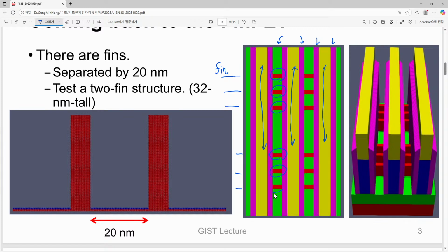Later, on top of these silicon fins, we will try to attach metal to have an ohmic contact. However, right now these fins are quite small in volume, so it does not provide us a sufficient amount of conductance.